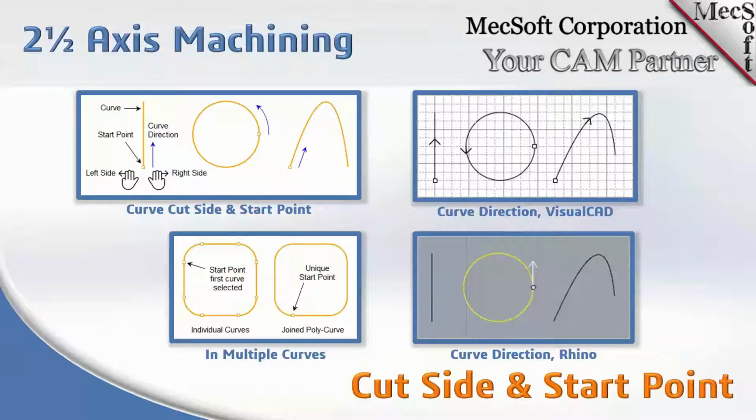So if you machine on that line, the start point is where the tool is going to start cutting. And the right hand or left hand, obviously, if you're standing at the start point and looking down the curve, right side is your right side, and left is your left side. And that's also the case in closed curves. A circle has a start point and it has a direction. So if you're going to machine the outside, that would be the right side of the circle in this case. If you machine on the inside, that would be the left side, or the inside.